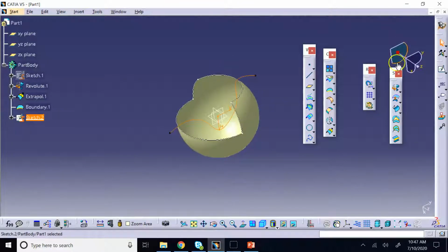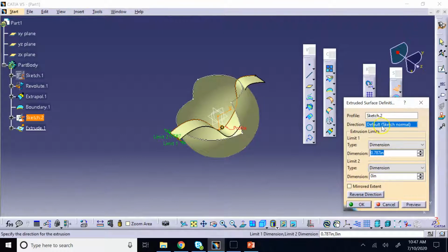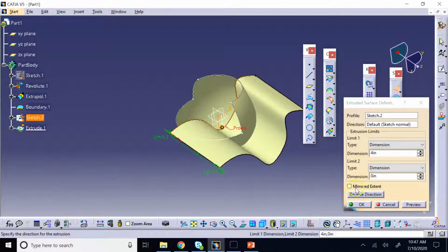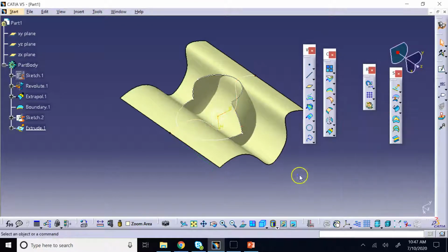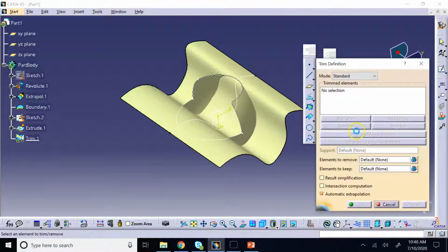Like that. Then I extrude it and make sure this new one cuts the old one all the way into two portions, like that. And now, remember, we had a split element and we have a trim element. So I say I want to trim this surface with this guy.